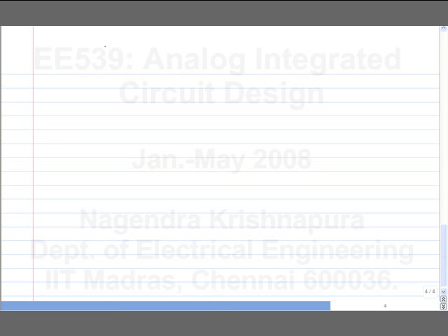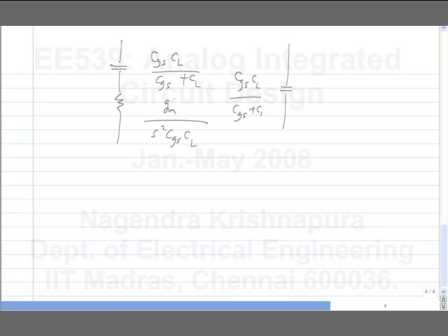We saw that again in the first assignment, if you recall. Let me reverse these. We have CGS in series with CL, in series with this frequency dependent negative resistance. This we saw was a parallel combination of CGS in series with CL and a negative capacitance, and a negative resistance.